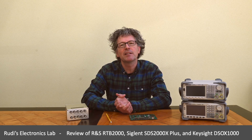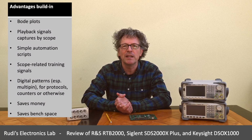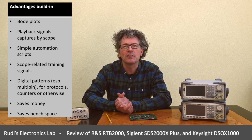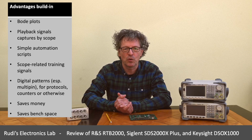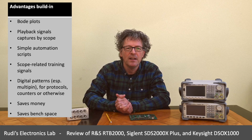One of them is Bode plots. All of the free oscilloscopes that we're looking at here can generate Bode plots, and that process is greatly facilitated if there's a function generator built into the scope, even though the Siglent SDS is also able to do it with a specific number of external function generators, and then they're connected via USB connection.